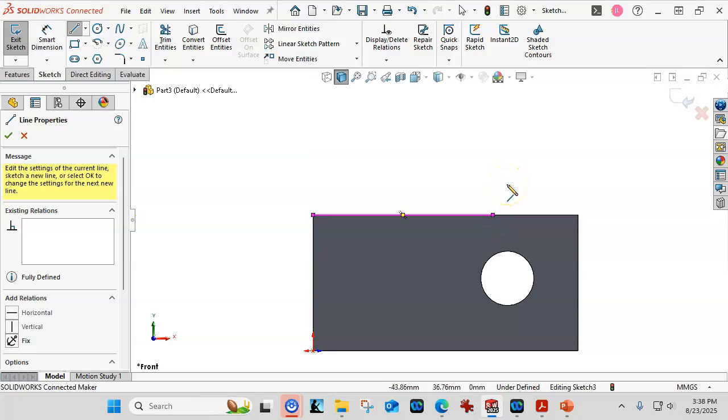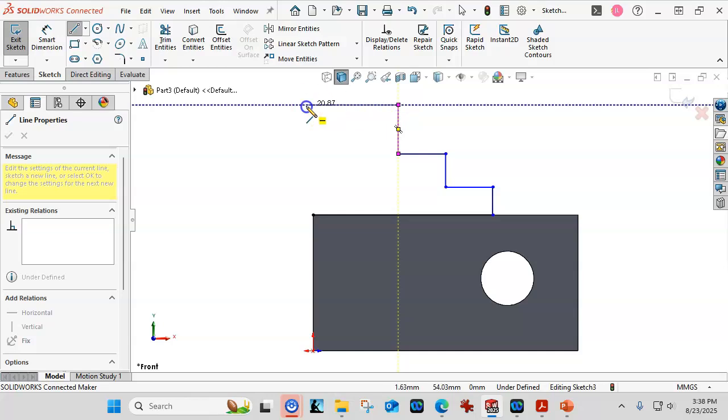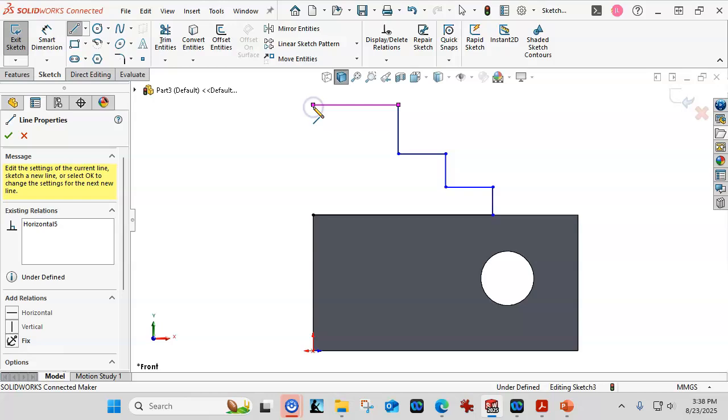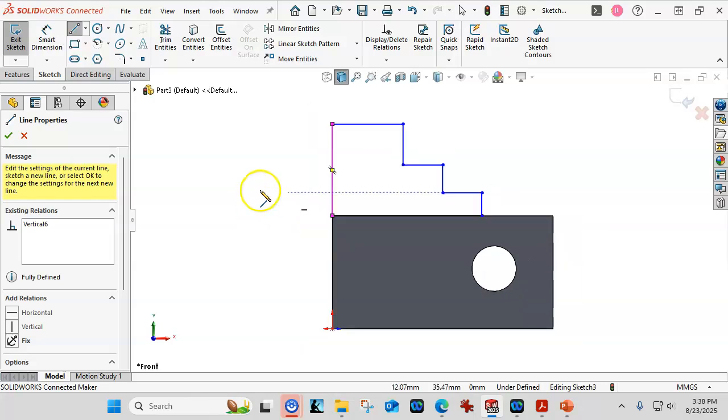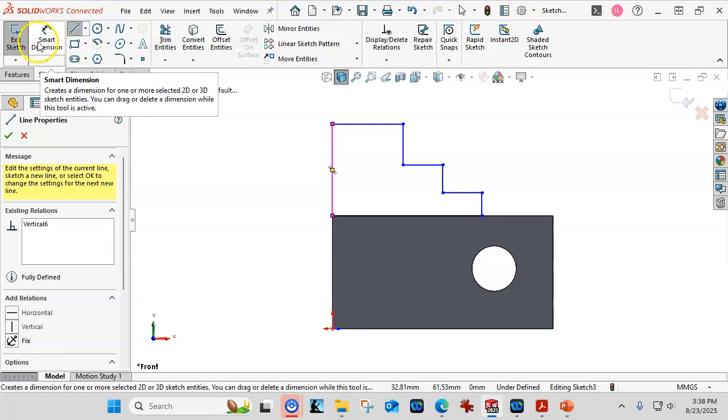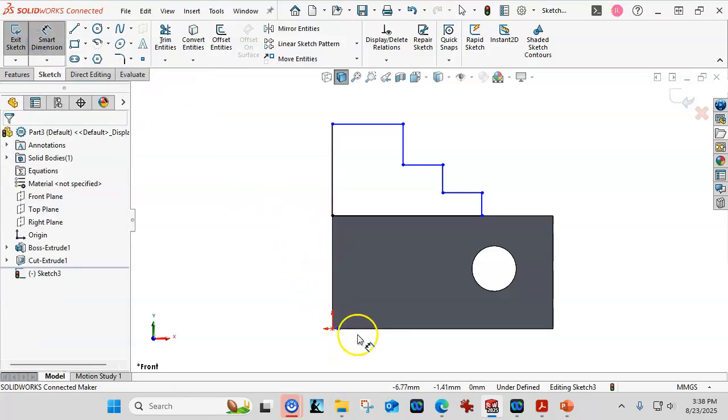And I did a click drag that time. So I slipped into click drag, and I'm click dragging. The advantage of click drag is it stops after each object, and I'm looking for that inference line. So I have horizontal, I'm above the starting point, and that puts me back. Do I care that it doesn't look exactly like what was going on in the example? Not really, because as we add the dimensions and we build this out, it's going to come into shape.